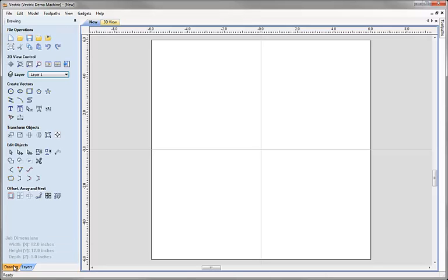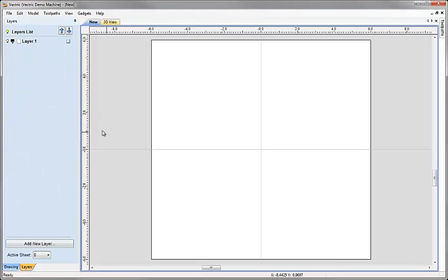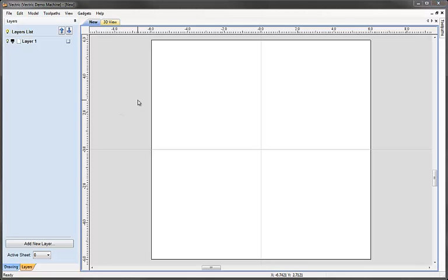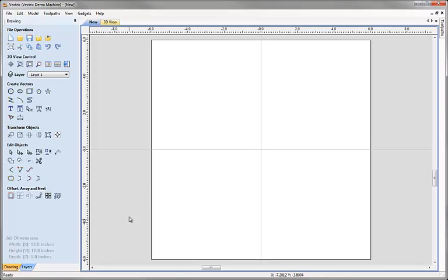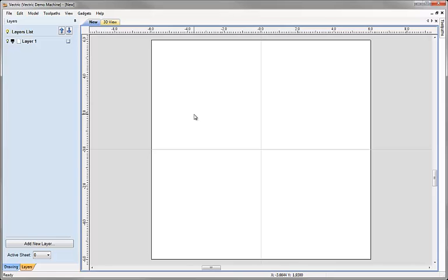Essentially the same information will be repeated in both those locations. So whether I look at it on the drawing tab and click on the arrow, or whether I look on the layers tab itself, I'm going to see the same set of layers listed here. Another way to access the full layer manager here, if you're on the drawing tab say, or maybe in Aspire you're on the modeling tab, or you're across on the toolpaths tab, is the shortcut key, and that's holding down Control on the keyboard, and then at the same time you're holding that, pressing L. When you do that, you can see that it automatically opens the layer manager for me on whatever tab I happen to currently be on.